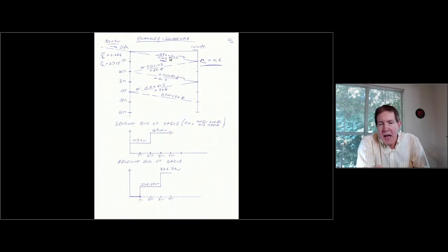What I would have is the 500 kV waveform come in from the overhead, and when it hits that discontinuity at the cable, we use the refraction coefficient of 0.286. So 0.286, which I put over here to the left-hand side just for bookkeeping, times 500 is going to be 143.